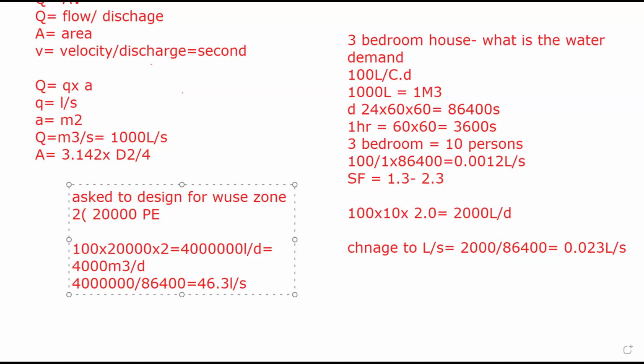PVC pipe has a very low frictional factor. If you touch the body, you see that it's very smooth. Unlike concrete pipe that has 1.0. These days, we don't use concrete pipe for drinking water again. Ductile iron is 0.4. It's still very good. Depending on the kind of lining, these days you see ductile iron, but it will be lined very well, so the frictional factor will still be low, which is a good thing. The lower the frictional factor, the easier water flows, and the less the losses. Understood? The smoother the pipe, the less the loss.